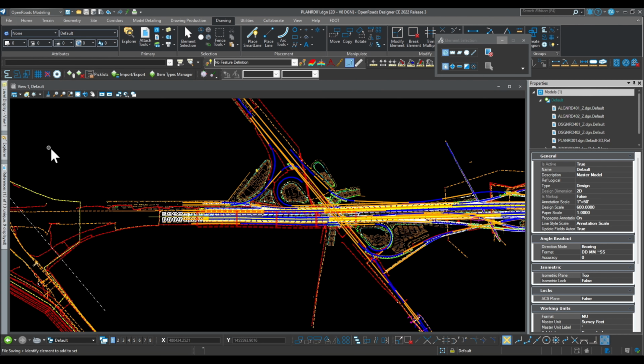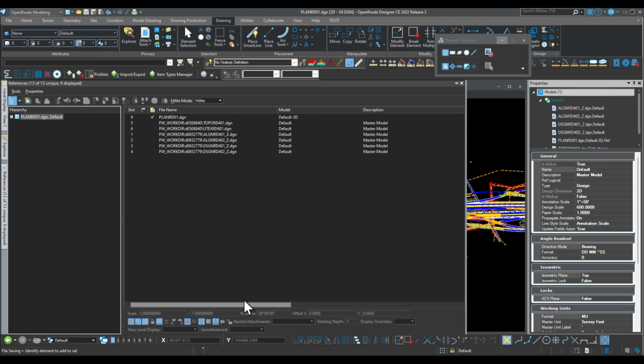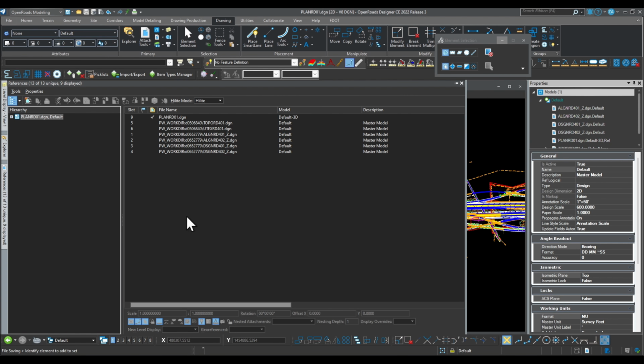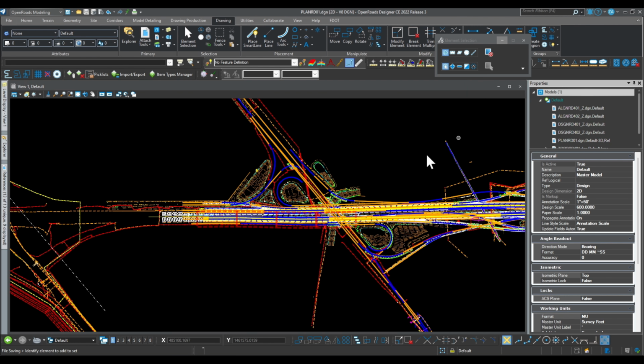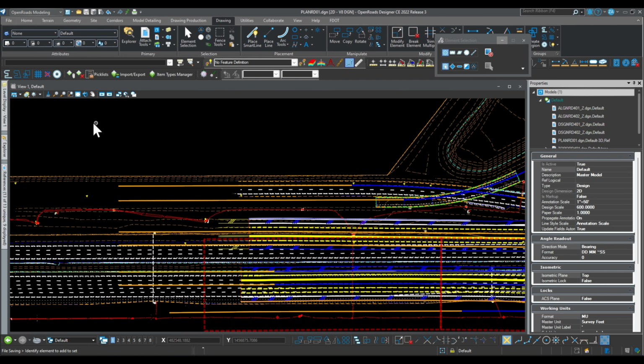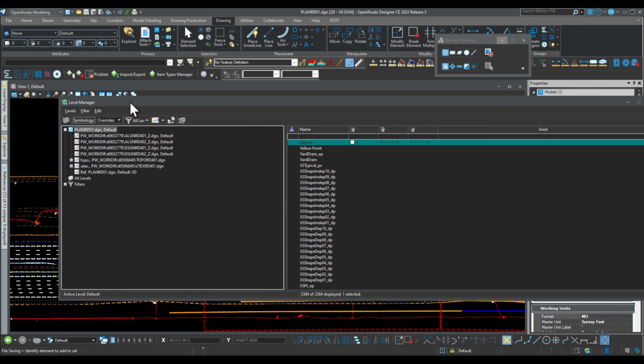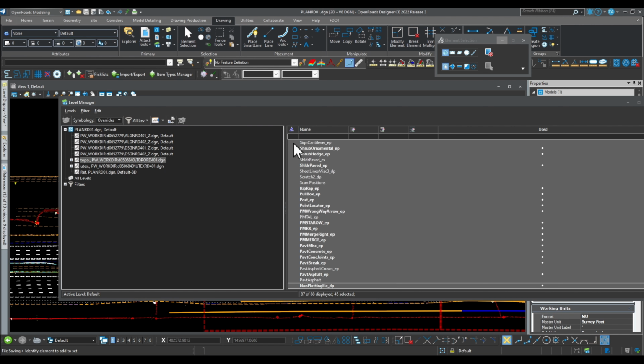Okay, so here's the thing. In case you're in Florida but you don't want to use this logic, you want to do the level override, or if you are in any other state, this will work with any workspace. It's something I do not like, but I wanted to show y'all how you can do it. So for example, I'm going to go here to the topo, click on this one and move down. I'm going to select everything, the used and unused levels, and then right click and do properties.